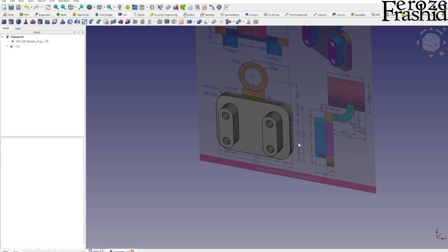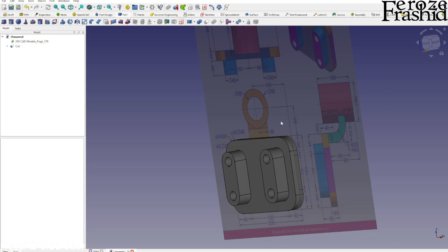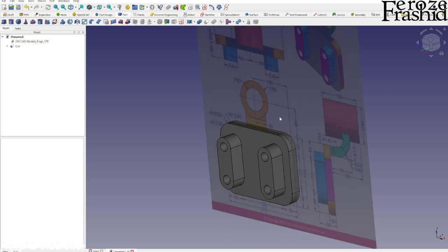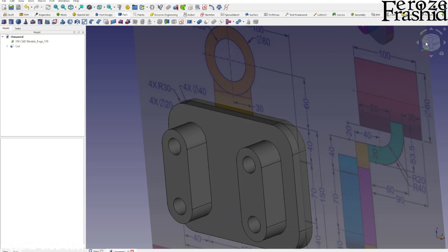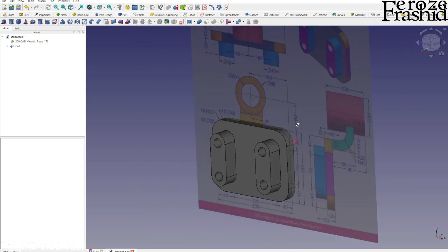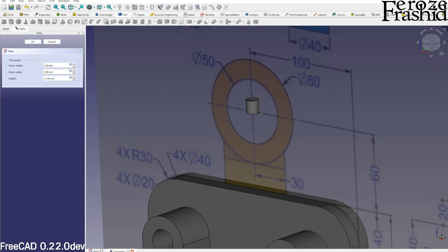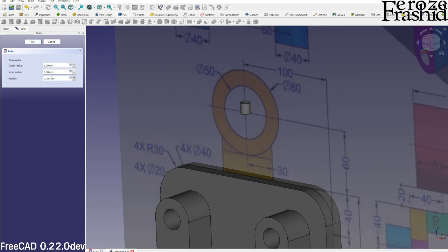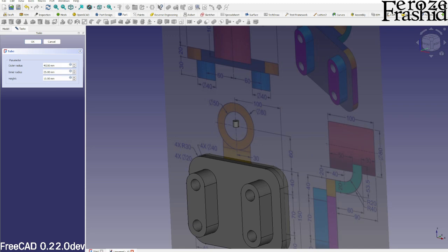But that's experience. That's a new way to build things. And as I said, I'm with you. Not the best user-friendly way to do it, but hopefully it will get better. All right, so one part done. Now let's focus on this tube. Because we have the center set up there, having a tube probably will be easy. There it is. I can say inner diameter would be 25 and outer radius would be 40, right? And then height, we know that the height is 100.